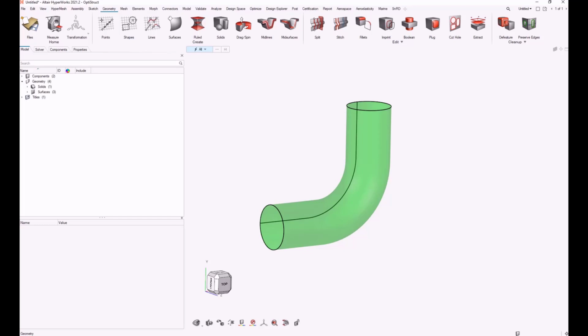In this video, I'll show you how to take 3D CAD, in this case, typical rounded tube geometry, extract a midline, create 1D elements, C-beams or C-bars, and then create the section property based on the input solid geometry.